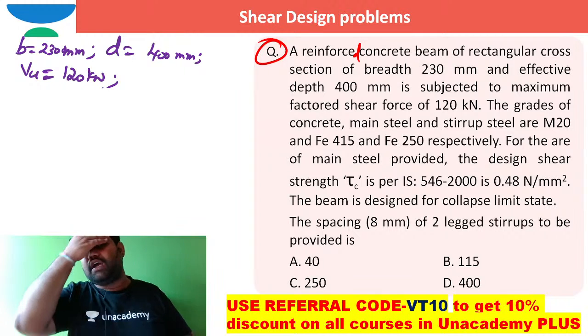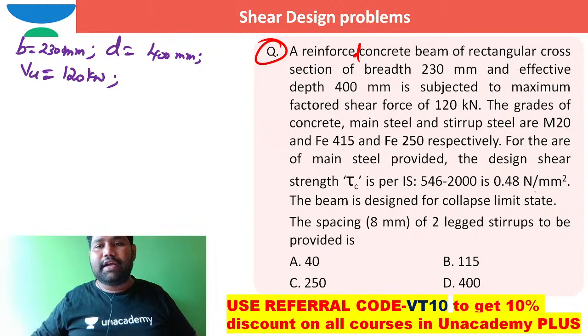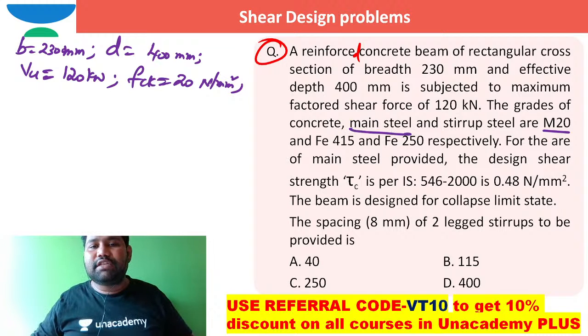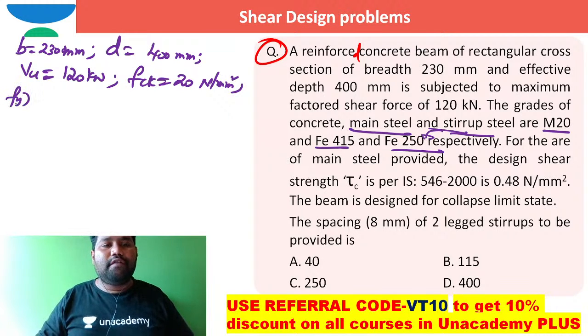The grade of concrete is M20, so fck is 20 megapascal, and the grade of main steel is 415, and stirrup steel is 250. So fy of shear reinforcement is 250 N/mm square.